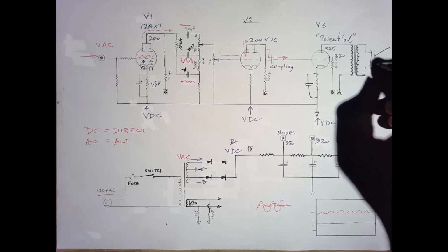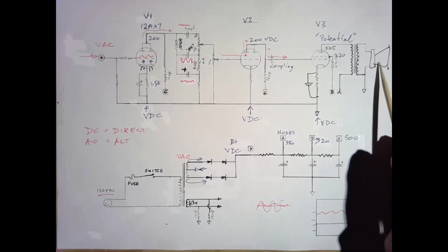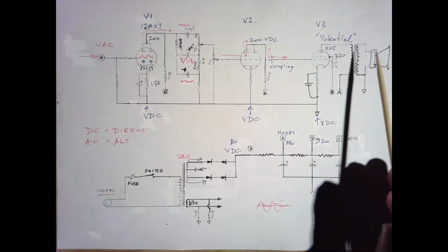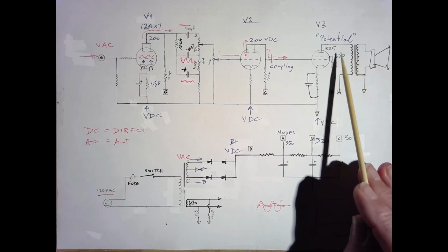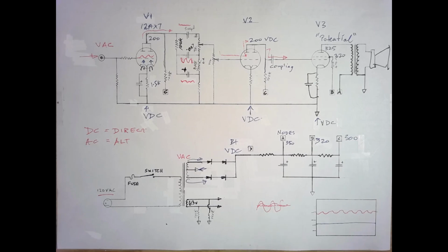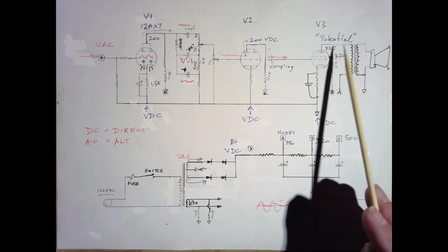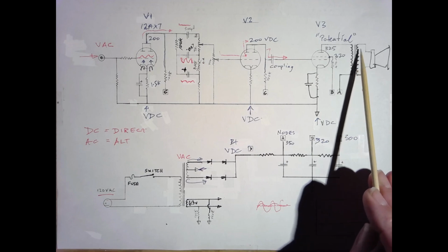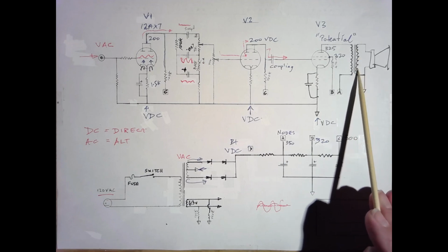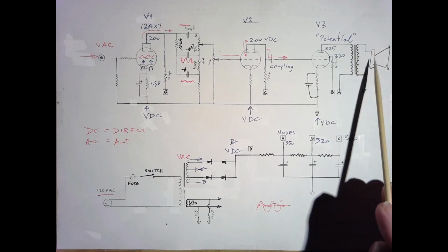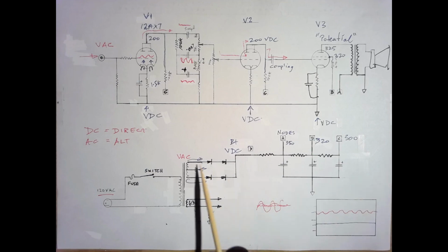So imagine that this is a speaker, and we would have an ohms rating on here. That could be 8 ohms or 16 or 4 ohms. And there's a relationship between these three things that when we get them in balance, it's perceived that we get the most pleasing harmonic tones, etc. But you can experiment with these things to your heart's delight. And you will know that some output transformers may have several taps, which means they just have a winding that comes up, and at a certain point they take off a tap and a bit more, and so on and so on. And that's an exercise in winding ratios, exactly as we saw down here.